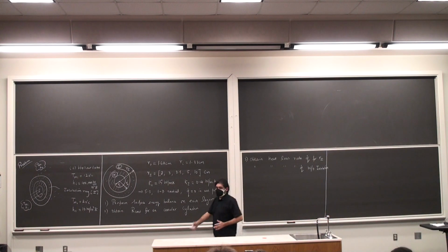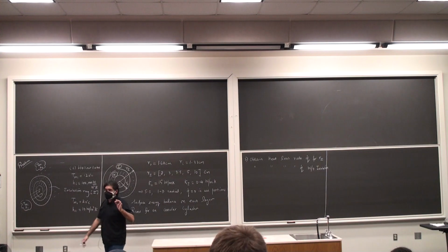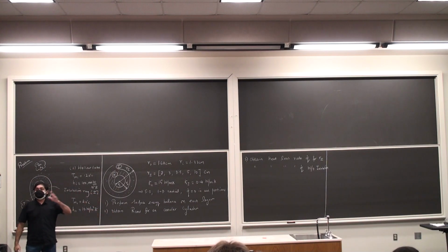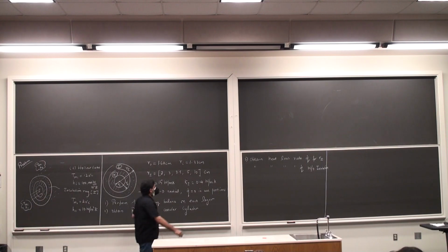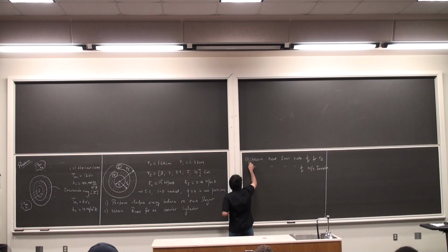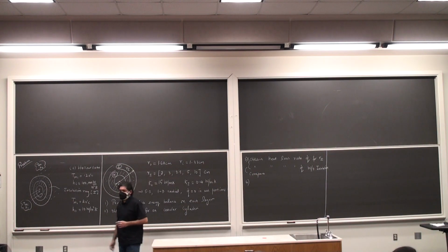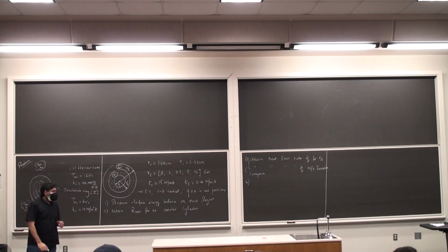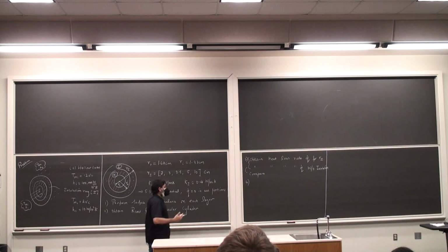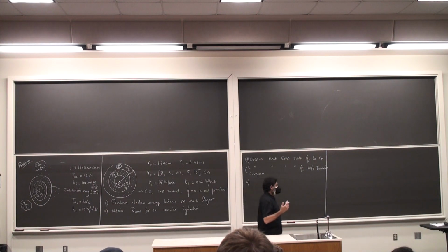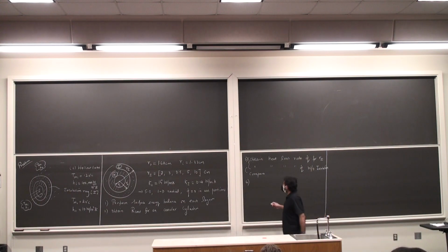You have to pick one radius for the insulation ring, perform the energy balance, obtain the heat loss rate. Pick the next radius, do the same thing. Okay? Then compare, which will obviously tell you some very odd things are going to happen. And so what our main aim, the centerpiece for the day, is we need to obtain the critical radius of insulation.